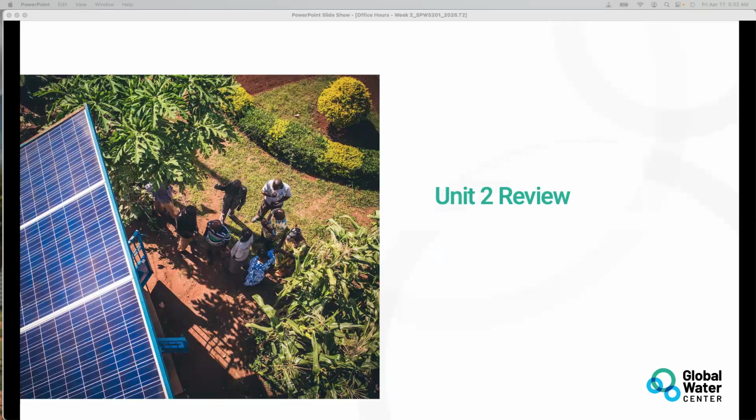For example, when you do the borehole schematic, even during pump test or well development activities, we need to know where the screen casings and the blind casings are located. And the other point is that when I see it on the diagram here, given in the module, the pump is positioned, of course, a little bit lower than the dynamic water level.